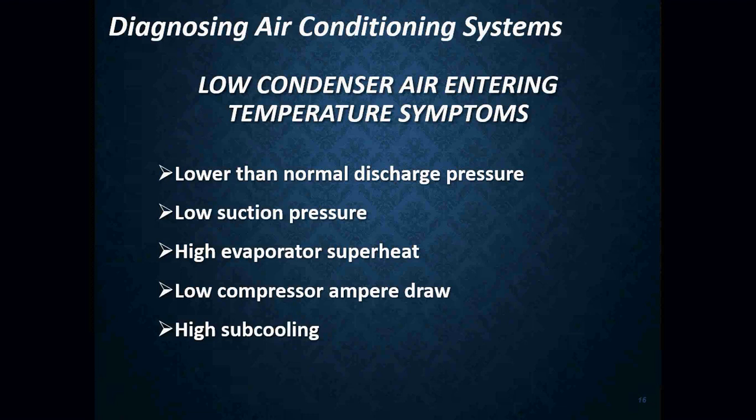We have controls in the field that will help take care of stuff like that, because air conditioners can run 24 hours a day, 7 days a week, 365 days a year, but I have to have controls on there to help maintain a certain pressure inside a system. Low ambient controls, for example. So we have to think about a lot of different areas so far when it comes to diagnosing an air conditioning system.